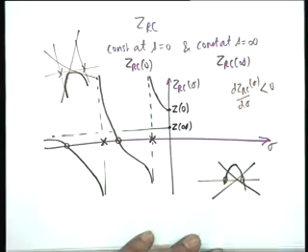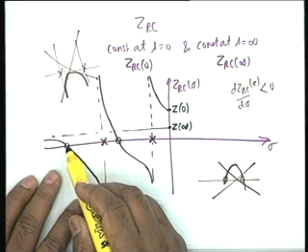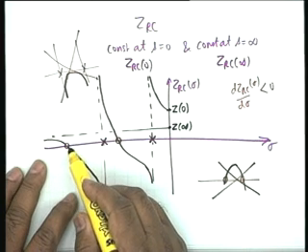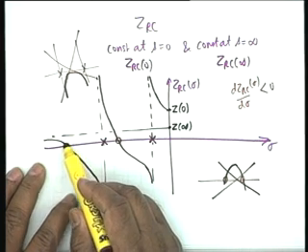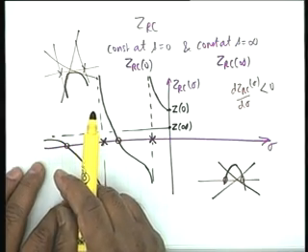So in either case it is a pole. The last critical frequency is a 0, irrespective of whether the function attains a constant value at infinity, or the other possibility, 0. If it attains a 0 value at infinity, obviously the last critical frequency is a 0. If it attains a constant value, then also the last critical frequency must be a 0.